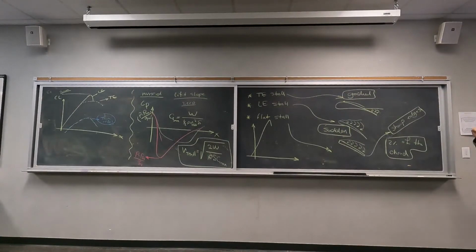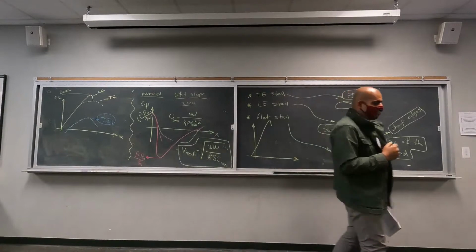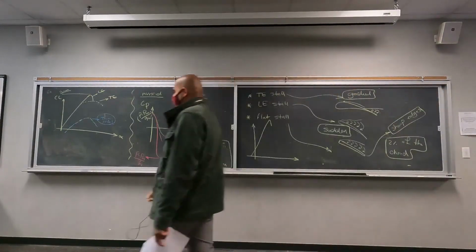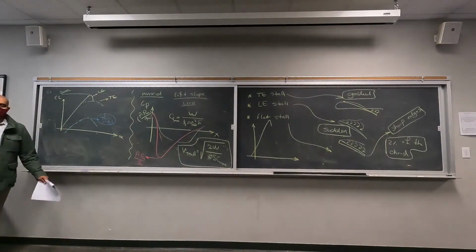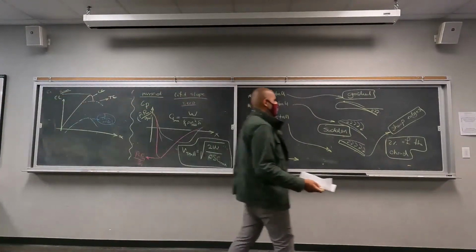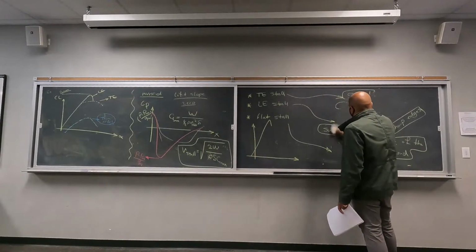How can we increase the lift coefficient at that stalling point or increase the angle of attack at which the stalling happens? Okay, so the main mechanism behind the stall was the flow separation, right? So you want to change the flow separation, right? We also have another mechanism to increase the lift. What was that? We actually have discussed this in the beginning of this chapter. Think about it. One mechanism to delay the stall is to come up with some sort of a design that delays the flow separation, or makes the flow separation a little less dominant.